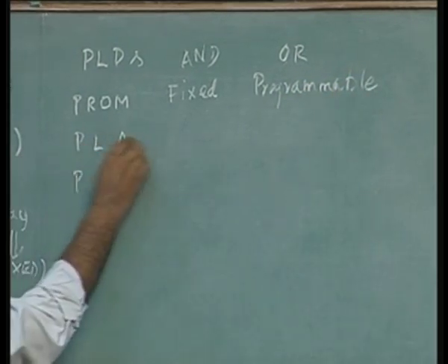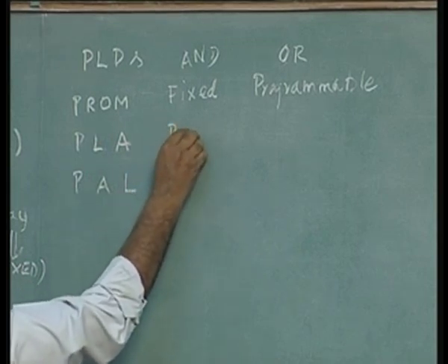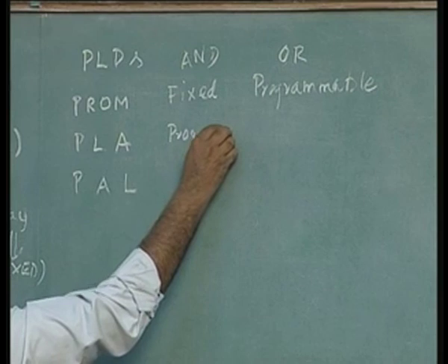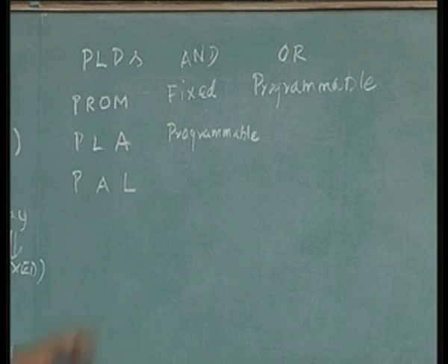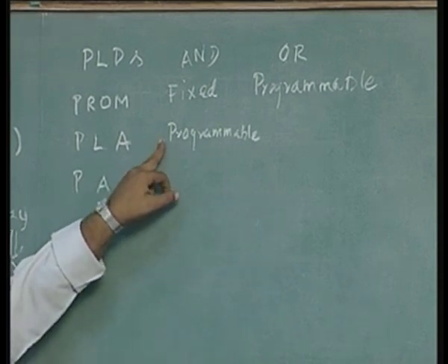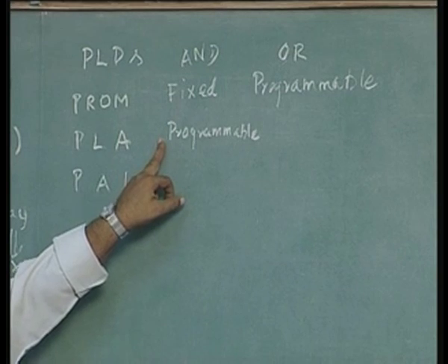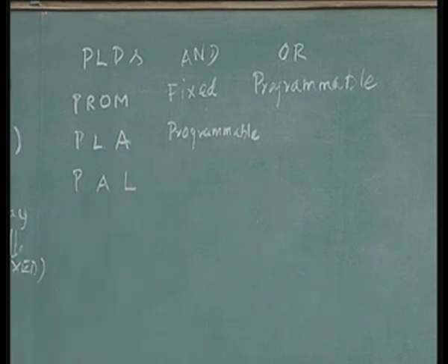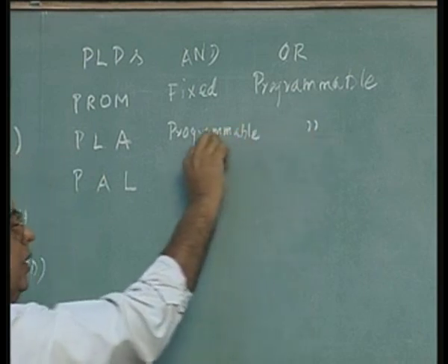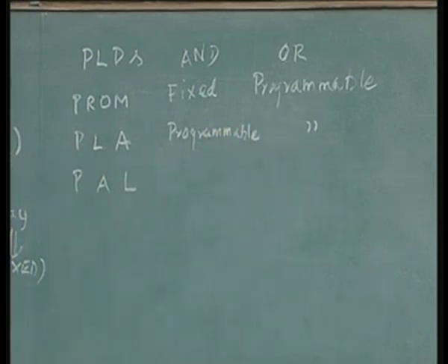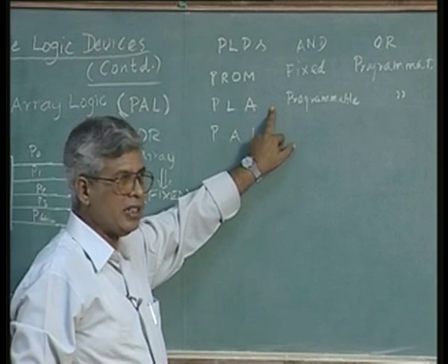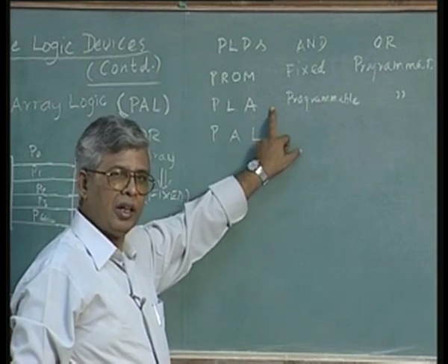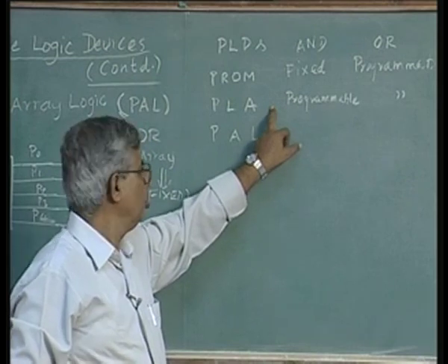In a programmable logic array, the AND array is programmable. You can generate product terms by any combination of the inputs by giving the appropriate inputs to the AND gates. And the OR gate is also programmable. You can combine the product terms so generated in any manner you like to form the output functions. The design concept here was to minimize the functions, but keeping in mind to have as many common terms as possible.